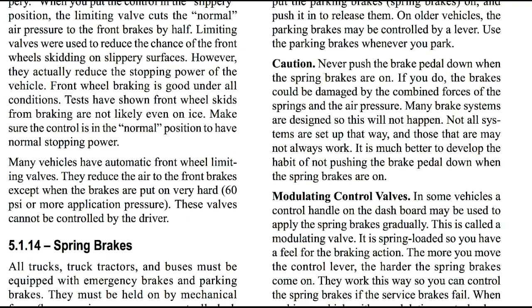Caution. Never push the brake pedal down when the spring brakes are on. If you do, the brakes could be damaged by the combined force of the springs and the air pressure. Now, many brake systems are designed so this will not happen. Not all systems are set up that way, and those that are may not always work. It is much better to develop the habit of not pushing the brake pedal down when the spring brakes are on.